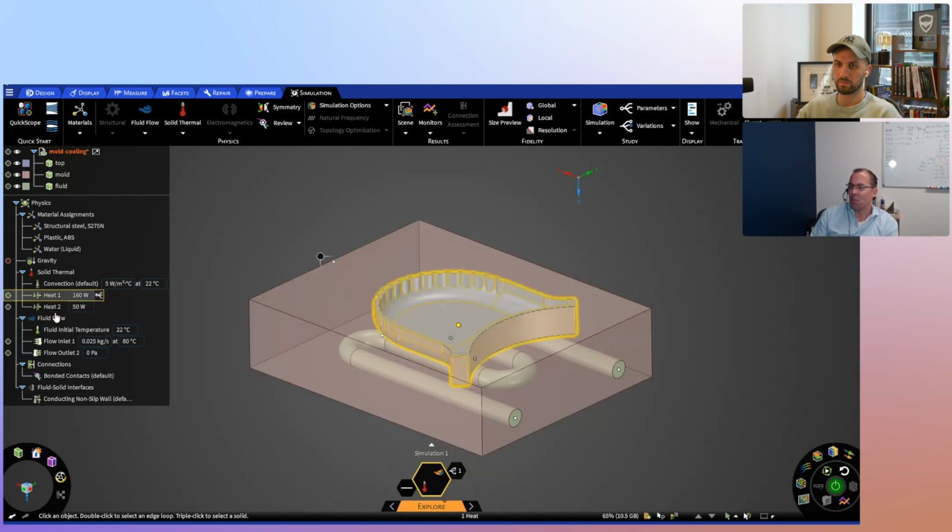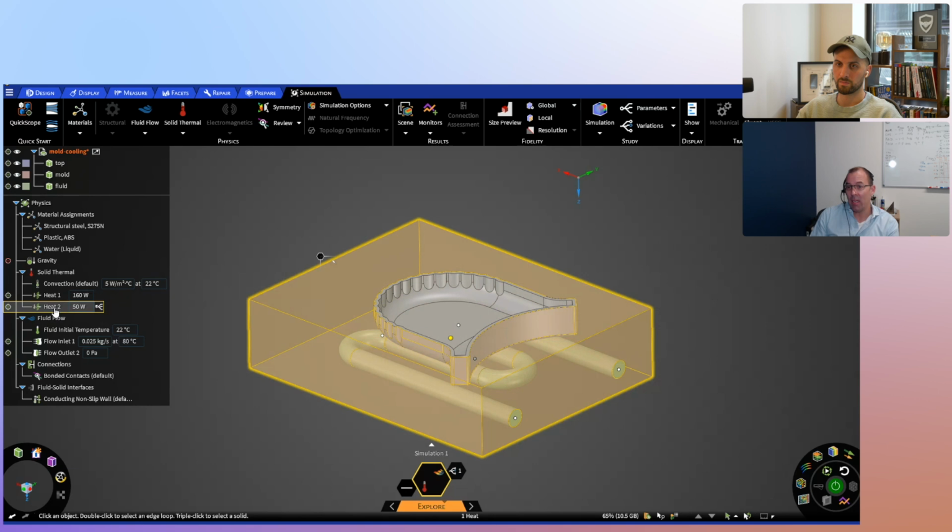Now, in a mold, we actually will have heating elements as well as cooling channels. It's really important to have the mold come up to temperature. We don't want to put molten polymer into an ambient temperature mold, because what's going to happen is it's going to freeze, literally change phase halfway through the mold. So we're very carefully controlling the temperature band of the mold itself.